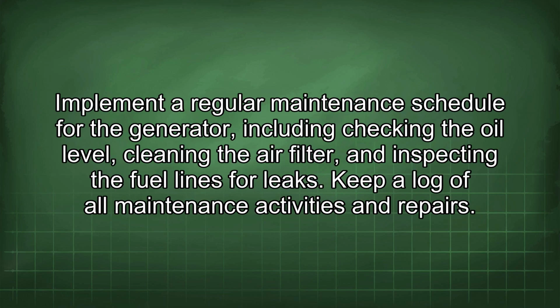Implement a regular maintenance schedule for the generator, including checking the oil level, cleaning the air filter, and inspecting the fuel lines for leaks. Keep a log of all maintenance activities and repairs.